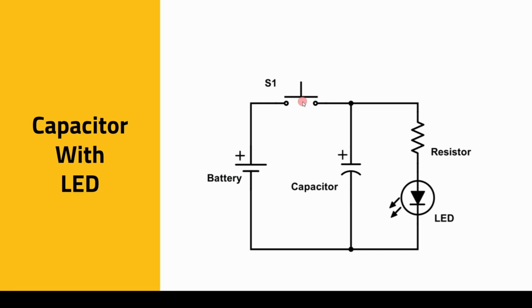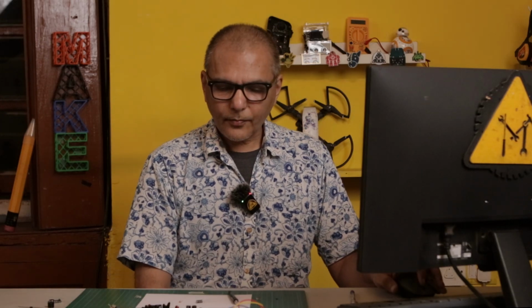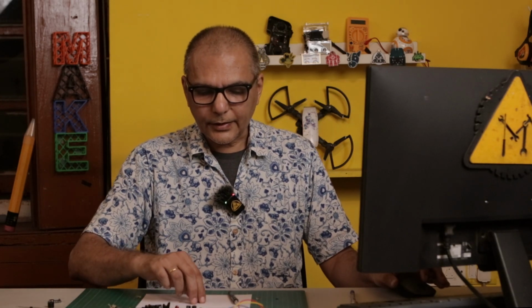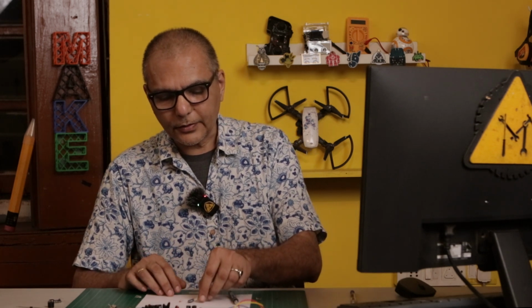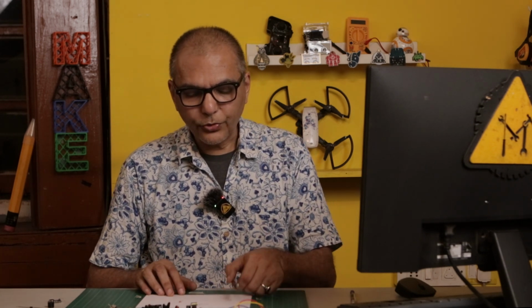And then as soon as you turn off the switch, there is a certain amount of charge stored in the capacitor because of its value, and the larger the value, the more the charge it stores, and then that passes through the resistor and the LED and keeps the LED on for a very short duration even when your switch has been turned off. So that's an interesting characteristic that is used. These kind of capacitors are used a lot in power supplies.